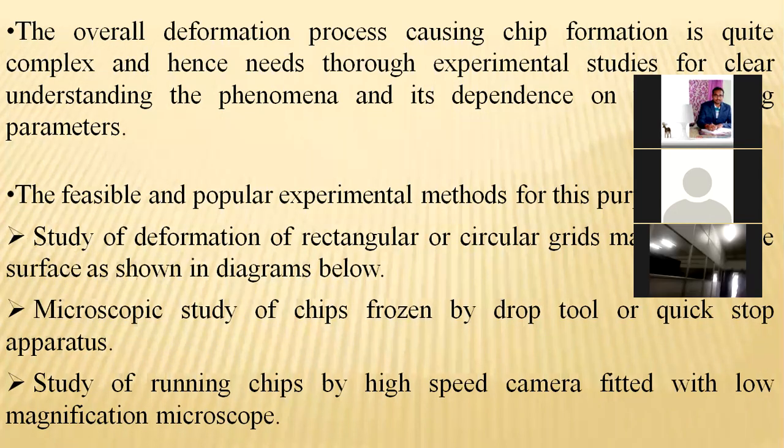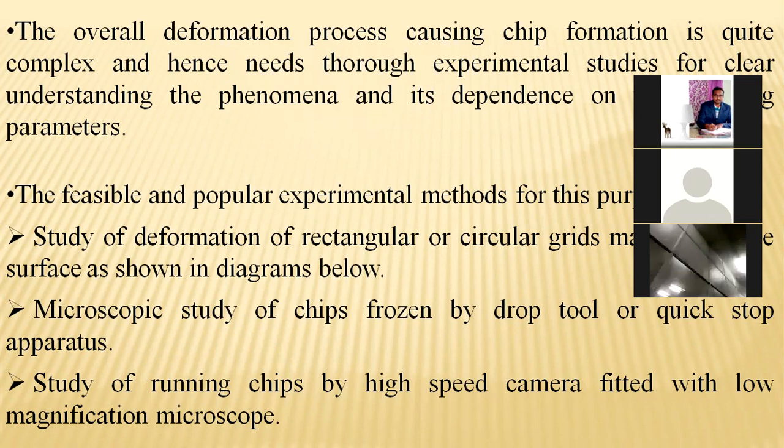So instead of doing the MRR process one time over a particular length, in the case of this turning machinery it has to be repeated 4 different times if you are utilizing 0.25 feed rate, or else if you utilize 0.5, the process needs to be executed 2 different times. And the next,